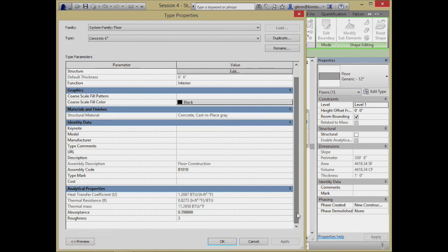If we have some sort of heating system in the building, forced air or radiant heat being used to heat the air, that floor is going to constantly be absorbing that heat and then re-radiating it at times when we're not heating the building. So that floor is like this big old buffer that just keeps on storing energy and re-radiating it and keeps things up.